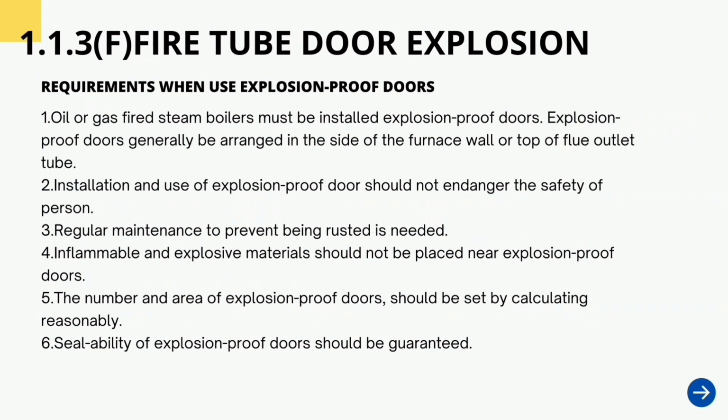Third, regular maintenance to prevent being rusted is needed. Four, inflammable and explosive material should not be placed near explosion-proof door. Five, the number and area of explosion-proof door should be set by calculating reasonably. And six, sealability of explosion-proof door should be guaranteed.